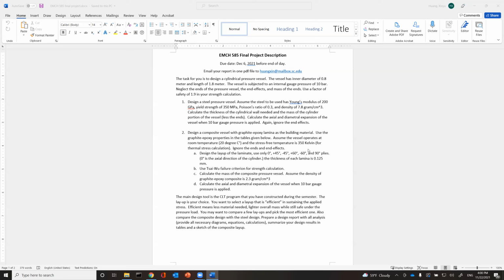Whenever you use an important failure equation, you need to point it out. Let's say you use a maximum distortion energy criterion, which is fine. For part one, you need to write that important equation out, with input and output from that equation.